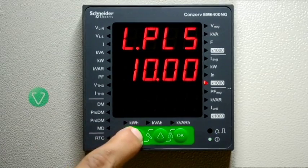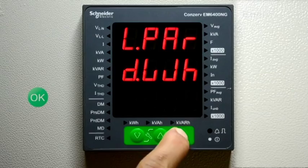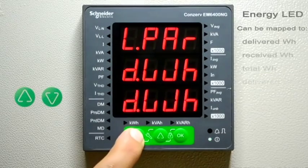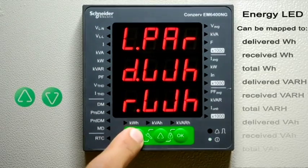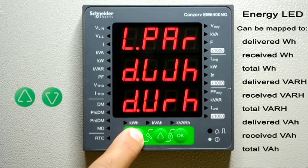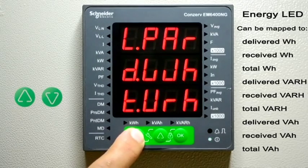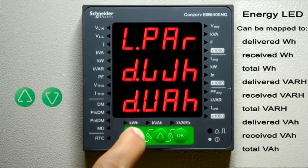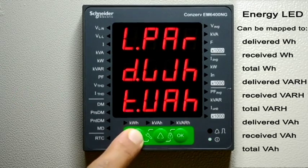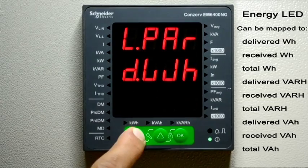Next item is the LED parameter. This setting is used to map the red LED to the required energy parameter. Red LED can be mapped to delivered active energy, received active energy, total active energy, delivered reactive energy, received reactive energy, total reactive energy, delivered apparent energy, received apparent energy, or total apparent energy. Let us map the red LED to total active energy.